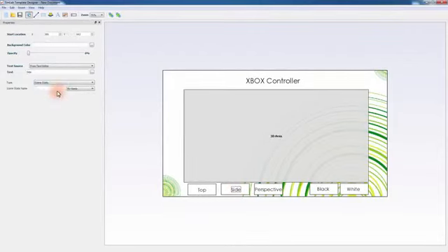You can also have the model tree open to display a list of all the components in your scene. You can set the navigation mode, render mode, and the default light type from this tab as well. Those modes can later be changed while the PDF document is open via the 3D toolbar. The Show SimLab Buttons bar option will display buttons to switch between your cameras and your scene states. Automatic transition will switch views between cameras automatically.